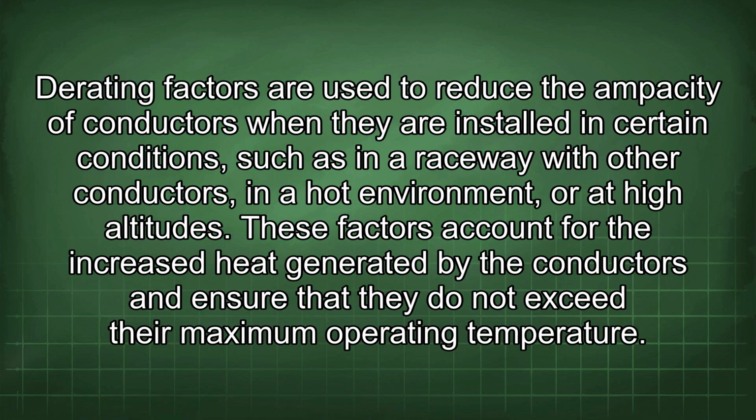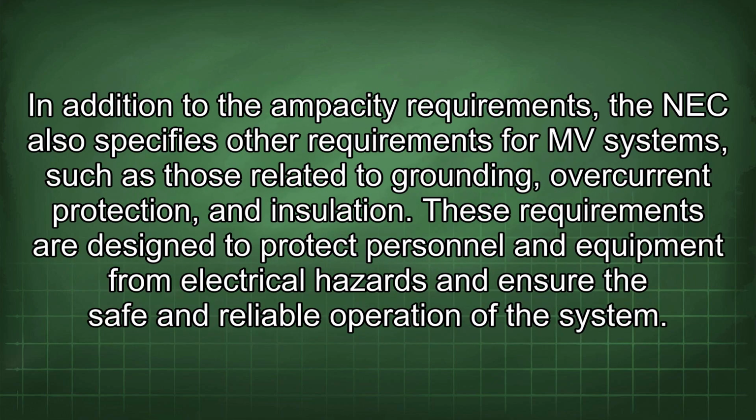Derating factors are used to reduce the ampacity of conductors when they are installed in certain conditions, such as in a raceway with other conductors, in a hot environment, or at high altitudes. These factors account for the increased heat generated by the conductors and ensure that they do not exceed their maximum operating temperature. In addition to the ampacity requirements, the NEC also specifies other requirements for MV systems, such as those related to grounding, overcurrent protection, and insulation.